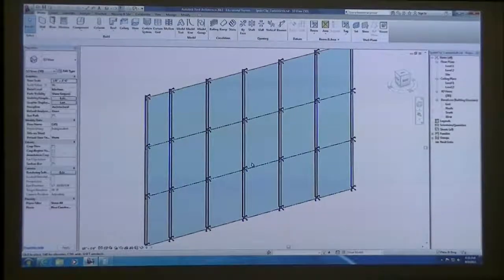So last class I started to get into working with the curtain wall system, and we just looked at how we could add mullions and deal with a real basic straight wall that you can divide up into grid systems, and then apply a typical mullion that you would find with like an EFCO or Kawneer system. Just your typical 2-inch by 6-inch or 2-inch by 7-inch mullion.